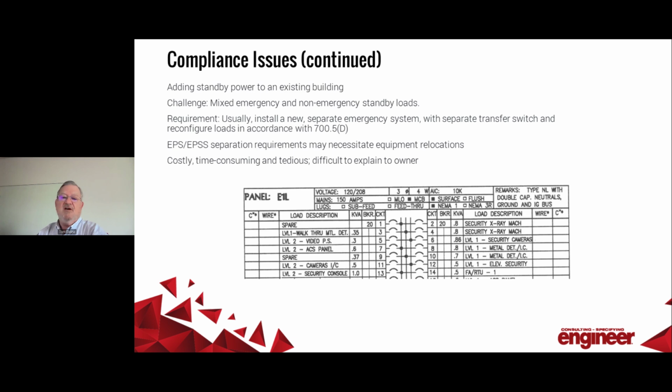The same issues can arise in older facilities built before this requirement existed. This slide is a snip from a panel schedule in an existing building where emergency and optional loads have been mingled. There are more than a dozen circuits shown there, and only one of them serves a proper emergency load, a component of the fire alarm system.